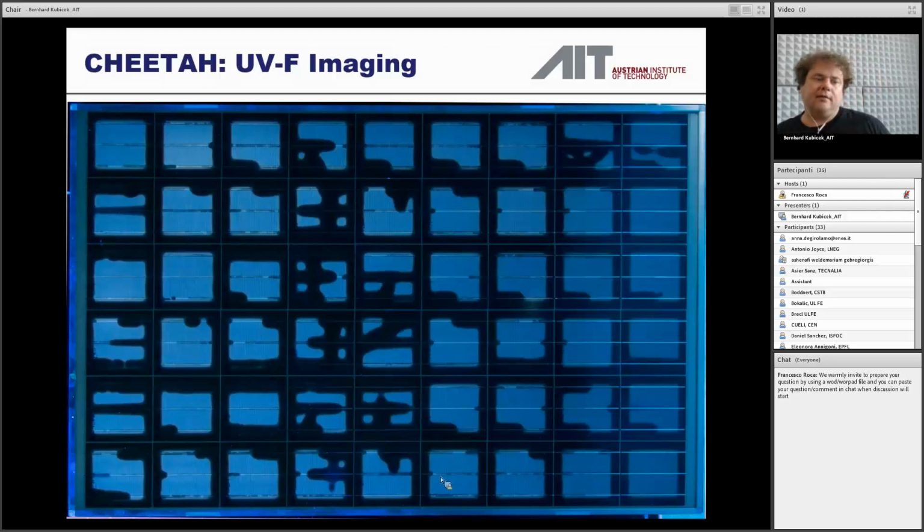However, and this is what I would like to make as a final statement, I think that UV fluorescence is quite novel. It's maybe showing a lot of defects that don't have any real impact in case of energy production, but you can analyze a lot of the modules. So for research centers, I think it's a very interesting tool. If you own plants, I think it's also interesting because you can do measurements at nighttime where you can see the cell tracks with the naked eye. I think even for that it's quite interesting.